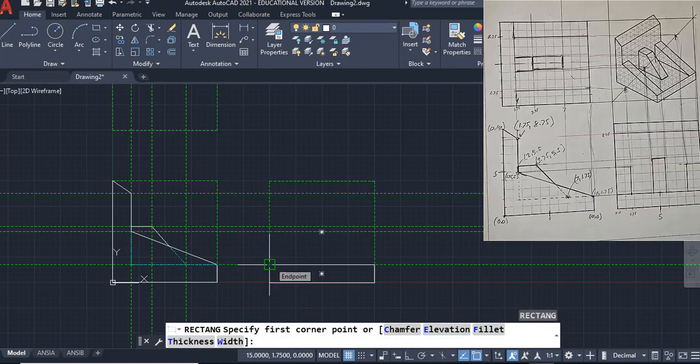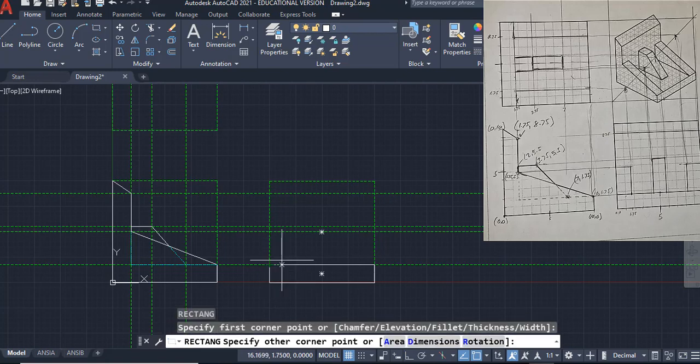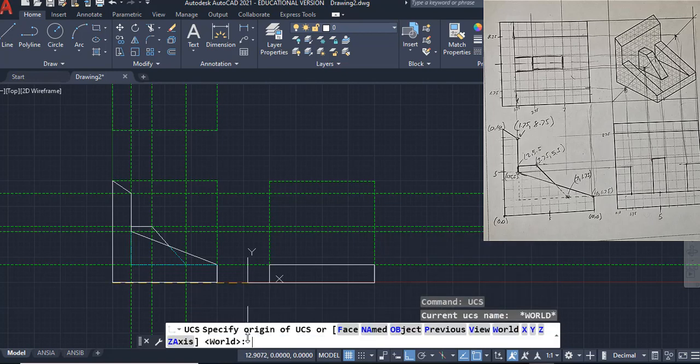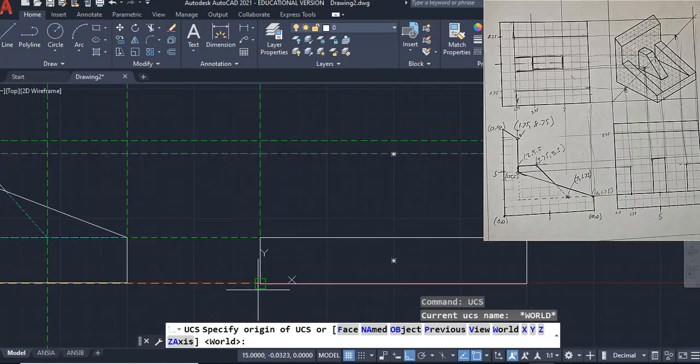So I'm coming up here. Here's my starting point is 15 and 1.75. And I'm kind of having to figure out what the coordinates are all the way over here. Let me show you another trick. I can actually move where my coordinates are, UCS, and I'm going to say, let's move it over here. So I'm measuring everything off of this new view.